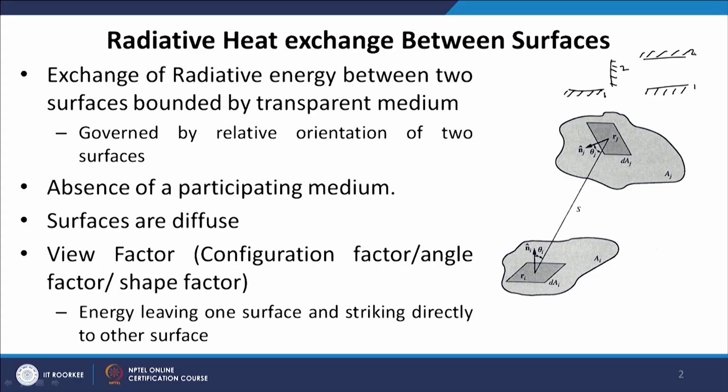With view factors, we talk about the exchange of radiative energy between two surfaces bounded by a transparent medium. So the condition for calculating the view factor is that the medium surrounding these two surfaces should be vacuum. We can also calculate similar factors when the medium is not vacuum, or is filled with gases that absorb and emit radiation, but that part we will reserve for later lectures. In this part we will assume that the surfaces are surrounded by vacuum, and we also assume the absence of